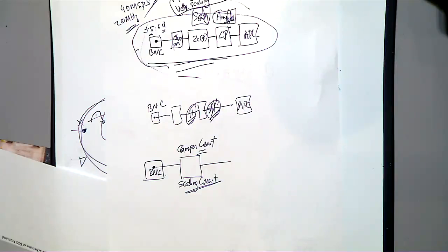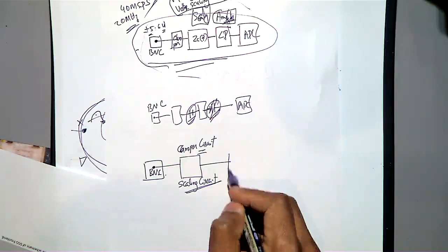Here we are connecting the buffer after the clamping. Why? Because you don't want to burn your buffer. If somebody connected 100 volt or some other high voltage directly to the buffer, the buffer would be damaged. That is the reason you have the clamping first, then the buffer, and this buffer will isolate this part from this part in terms of impedance. So it's a good idea to connect a buffer circuit.